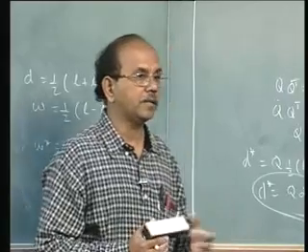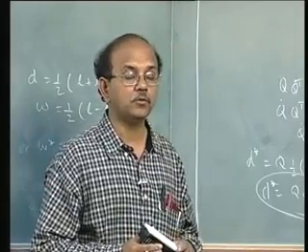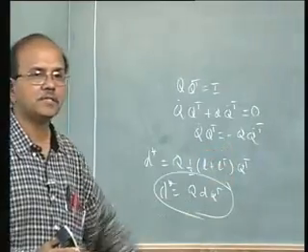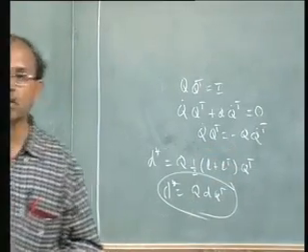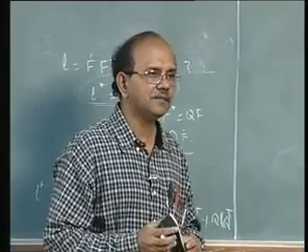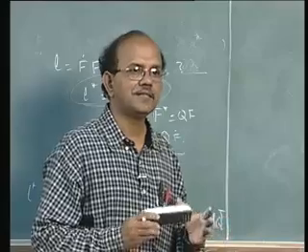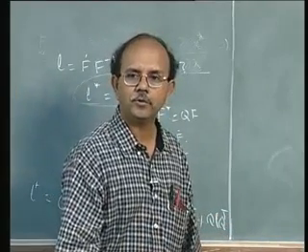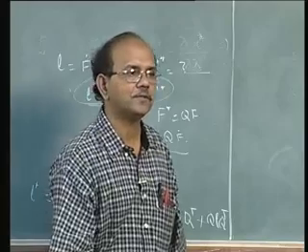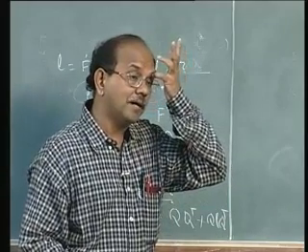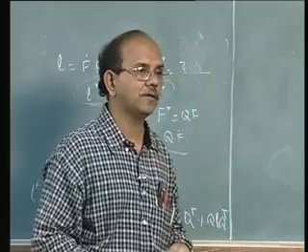So we know what type of quantities we have to use, but we are stuck at one place where we showed sigma dot is not a material frame indifferent quantity. Right? We are stuck because we want some rate quantity which can be used in the constitutive equations. We do not seem to have it. Okay, can someone suggest what can be done? I will give you a clue.